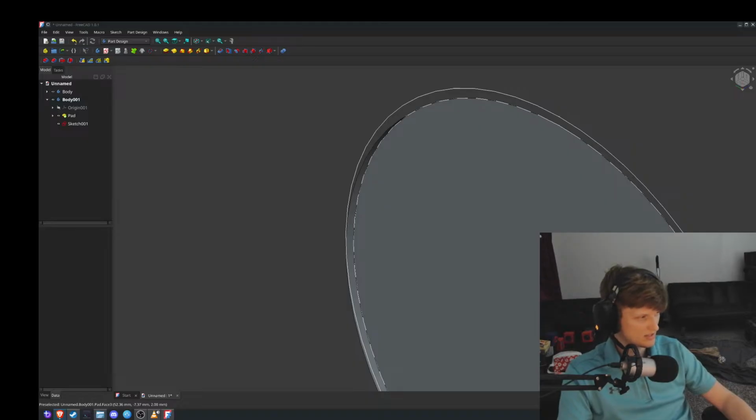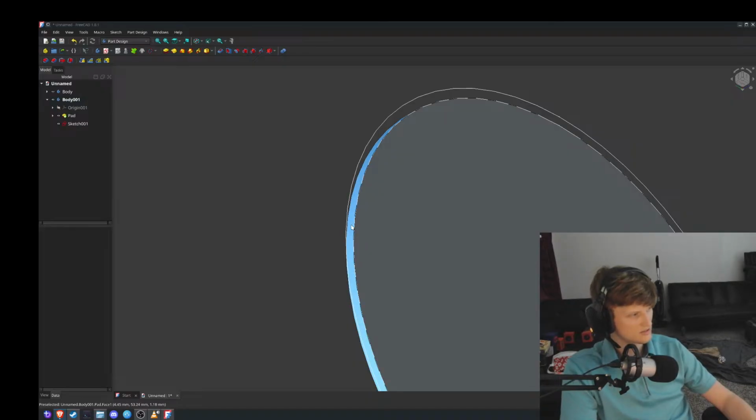But the problem with that is that that's two steps, and I want to do it in one step. Like, come on, people. One step is all we should need. One step. Switch to the part design tool. Select the sketch you want and use the pad extrusion to extrude the closed profile. Enter the desired extrusion length in the dialog that appears.